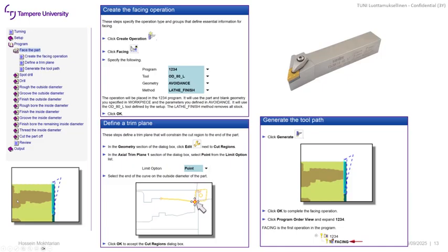All right. The first one is perhaps, for example, the facing. So in the facing operation, we need to use a correct tool. It's the outside diameter tool that we're going to use. Again, here we can decide about it. Do we need to do the facing roughing first and then finishing, or are we considering that the last pass of our operation is already in the finishing stage?